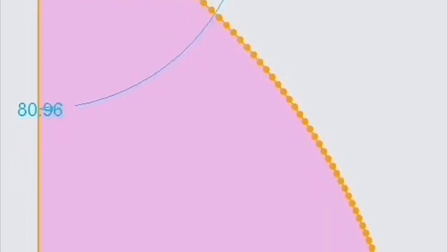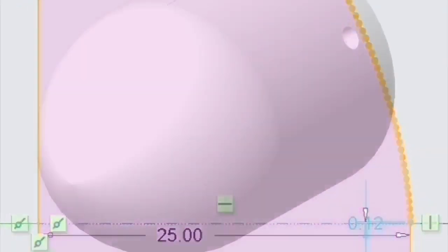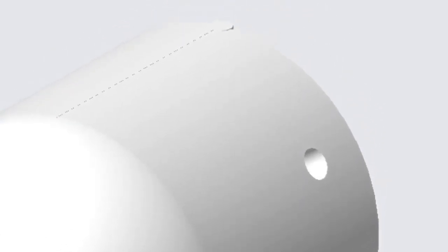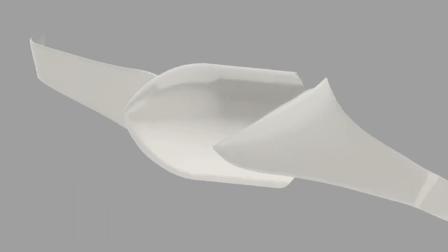This was primarily due to the fact that, following consultation with a department technician, we found that the 3D printer's resolution would be inadequate to reproduce the 2mm deep dimples, therefore making their intended effect insignificant. Instead, the use of Haack coordinates compensated for this by reducing the nose cone's drag in its own right.